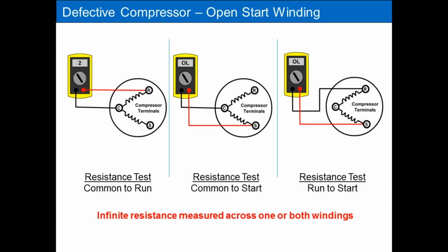But if you don't see that little M on your meter, you're in a dark location, and remember, sometimes you're working upside down and backwards on a floor and not in a very well lit area, you may overlook the little M on your meter, meaning you're reading in the million ohm range. Don't let that fool you. It's fooled me, so I can only imagine it's fooled some other people as well.